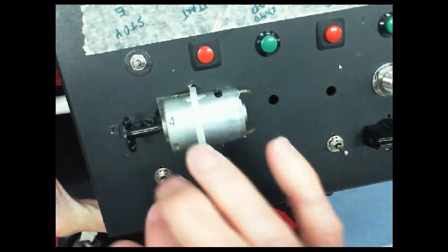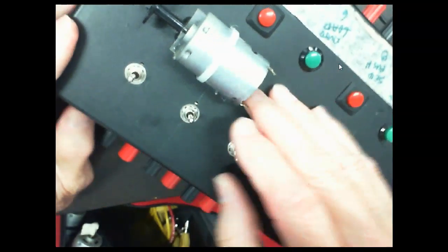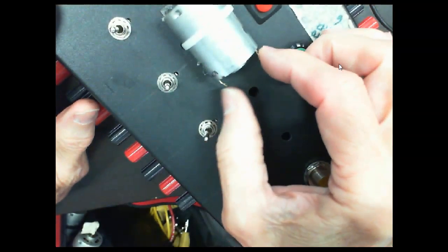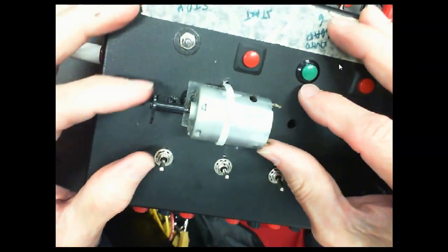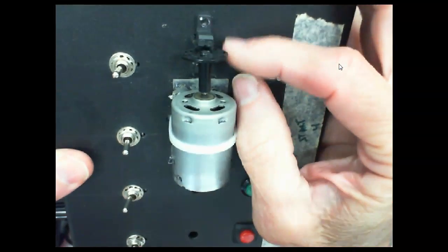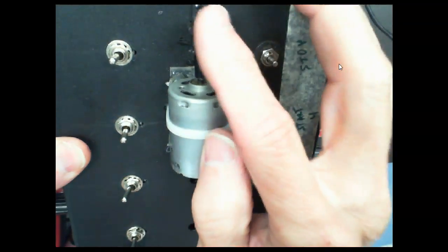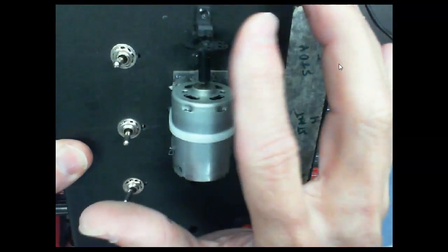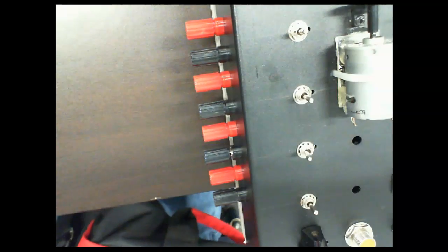And this is actually an encoder. What we would normally use with this is we would hook up just a DC power supply where we control the speed. And this encoder, I don't know if you can see it or not, but it's got a bunch of little slots in it. And when it spins, it goes to the sensor right here, which we'll talk about. And it will get a pulse for every one of them. We can use that to sense position, but we can also use it to sense speed. We won't use that this class.